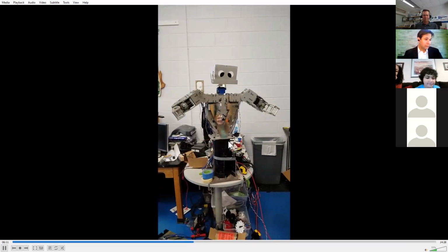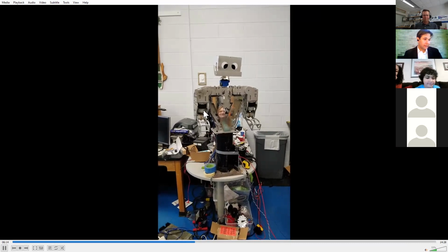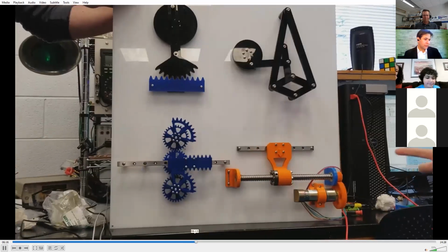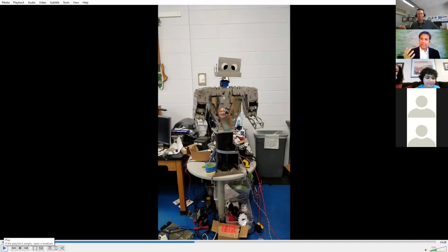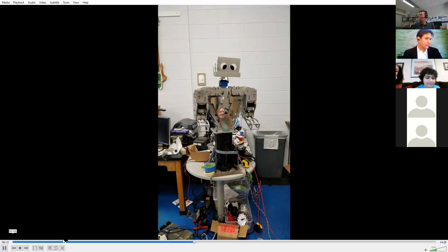All this is being controlled off of a Propeller 1 chip right now using the ClearPath motors by Teknic. Those are kind of neat motors. They're DC brushless motors, but they can be controlled like stepper motors with a microstepper driver. So you basically can just set a direction high or low and then just send them a pulse and they'll make a step, but they've got all the benefits and power to weight of a closed loop DC brushless motor system. So it's kind of neat. They're about $300 to start with for the NEMA 23 size. So a Propeller 1 is controlling those. And then we've got another little, they put a head on it just to kind of make it look cute, with this running off of RC servos.